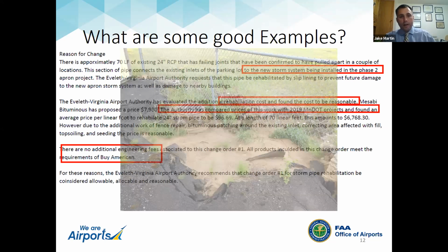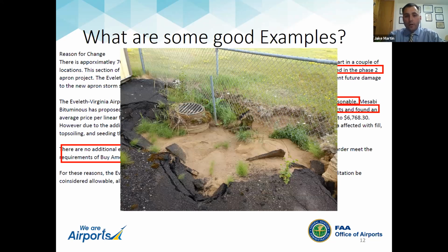And so this is the issue we're trying to avoid here: we come in and pave, put this pavement in, and everything where that bituminous looks fresh, it fails because there's some issue going on with the catch basin below the ground that might be outside the footprint.